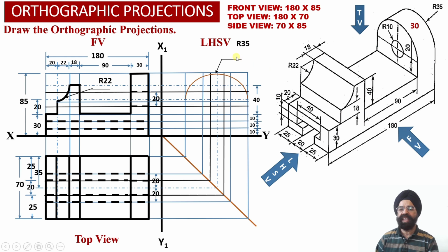So now the radius we have taken as 35 millimeter over here. Another thing we know, corresponding to the base of the circular portion, we have been able to draw another horizontal projector line into the left hand side view projections over here. So now as we are going to look at the solid from the left hand side, this T slot will be visible to the observer into the element number 1. So into the element number 1, which is a horizontal web, we have been able to obtain the projections corresponding to this T slot into the left hand side projection view over here.